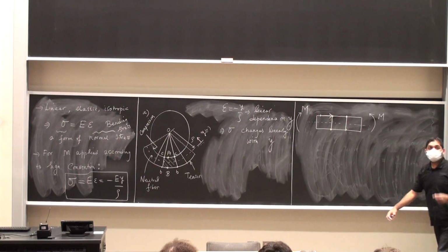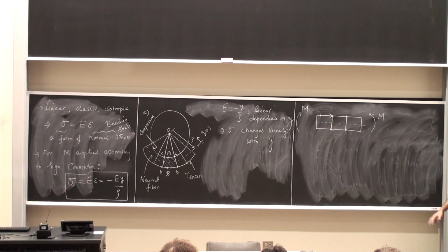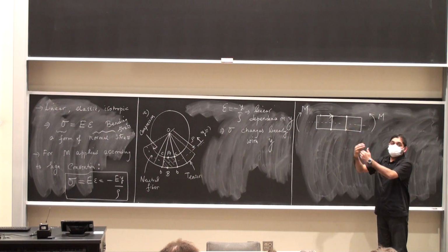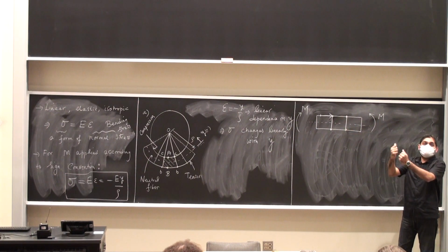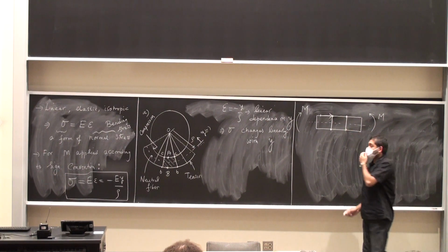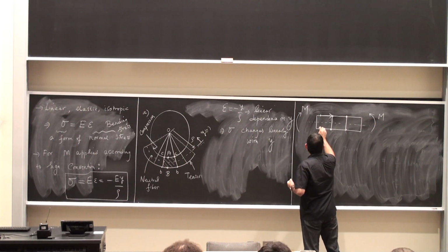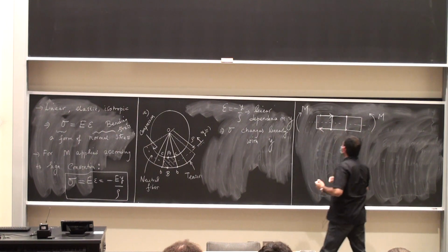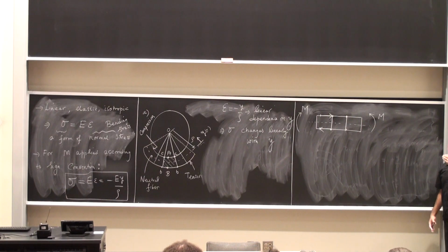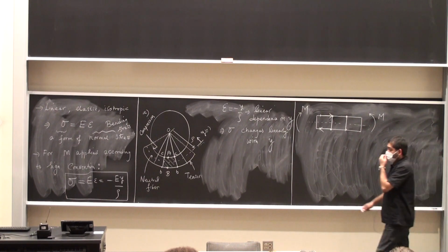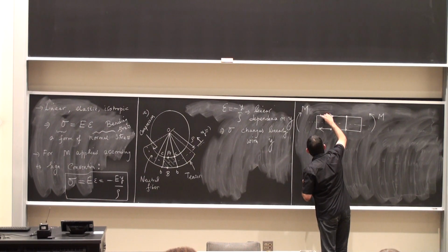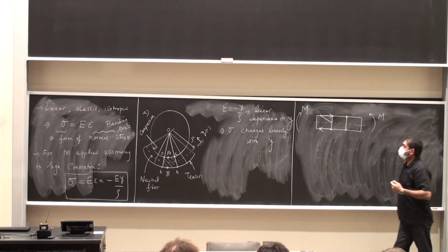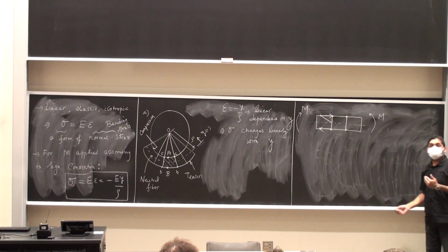But it's going to be a compressive stress, and you'll see what I'm talking about when I draw a three-dimensional view of this. Compressive meaning that it's trying to take this point and push it in. Tensile being it takes a point and tries to pull it out. So the stress here will be tensile. And these stresses will linearly decrease to 0 at the neutral fiber, and they will linearly increase as you go away from the neutral fiber below.